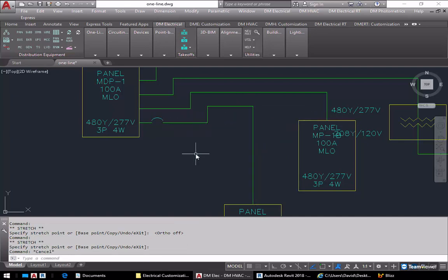I'm going to go ahead and create a block that is a circuit breaker plus a meter, because say you have a meter center and basically all of your feeders have a meter and you'd like to show that. Our software doesn't really address that very directly because it's kind of outside. It doesn't impact what we're doing terribly much. So you just need the graphic on your one line. So we'll go ahead and create a circuit breaker that also has a meter with it, so that then you can put that in as your circuit breaker block and it'll kind of be labeled automatically.